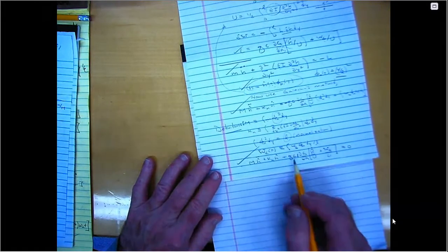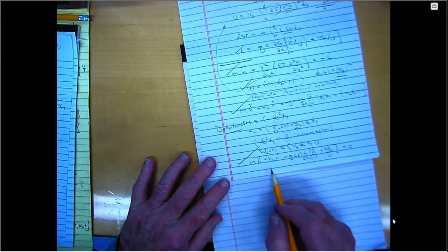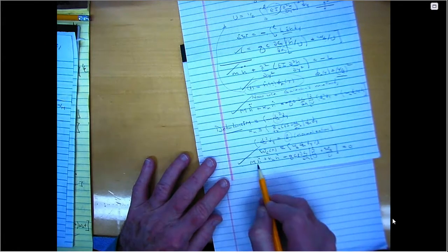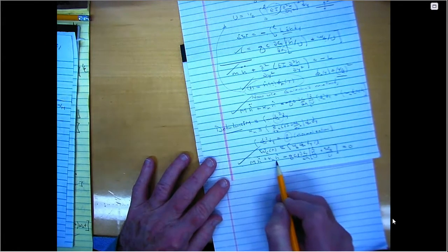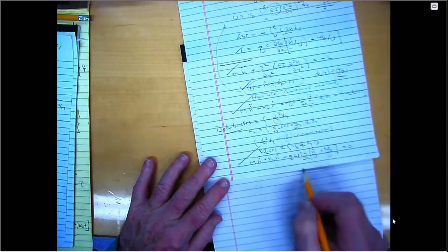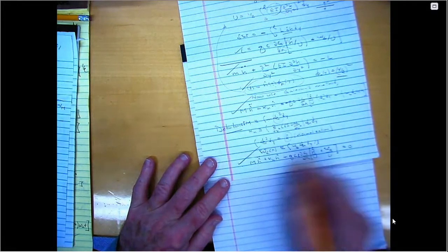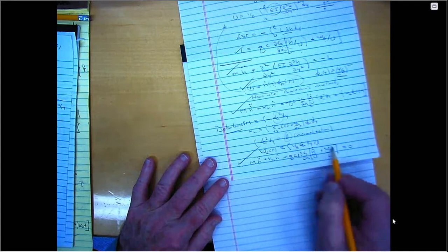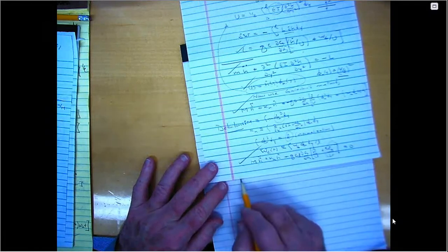And what does this look like? This is a spring mass damper system. Here's the mass. Here's the spring. Here's the damping. The damping came from the lift, right? This is aerodynamic damping. And then this whole system, the spring mass damper system, is forced by a lift force associated with the gust.